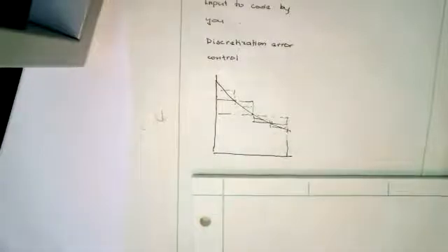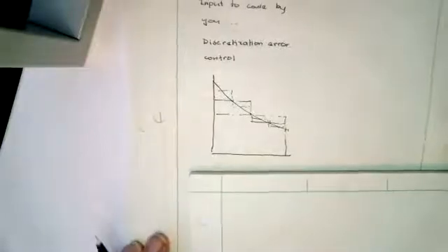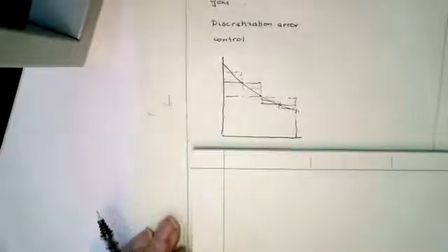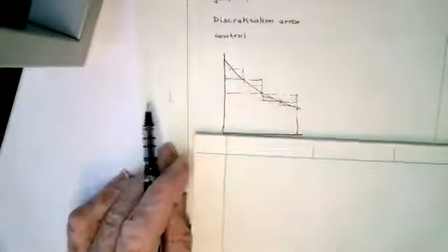But this sort of constant approximation is the one used for stresses with 4-node quadrilateral elements. Okay, so as the stress varies, you have constants, but as you make the size of the elements, these lengths, get smaller and smaller, you'll get it more and more accurately.